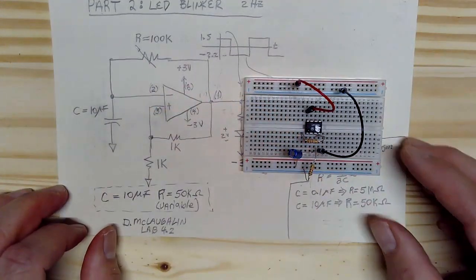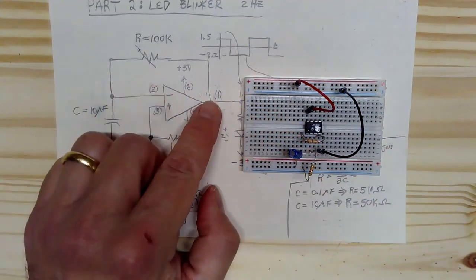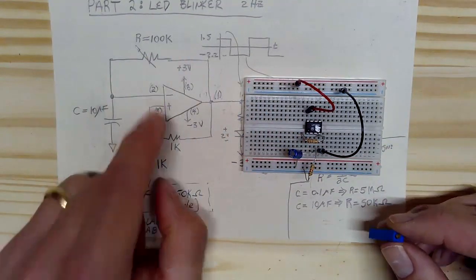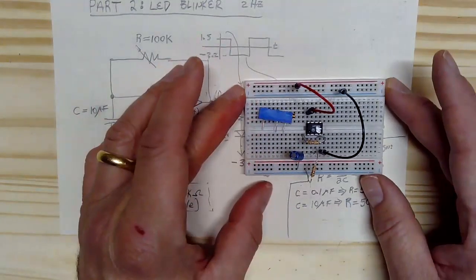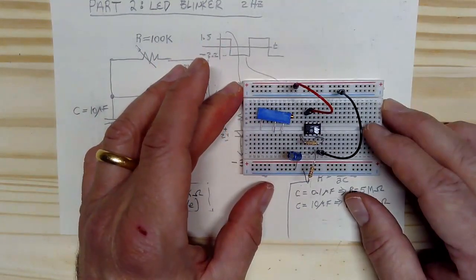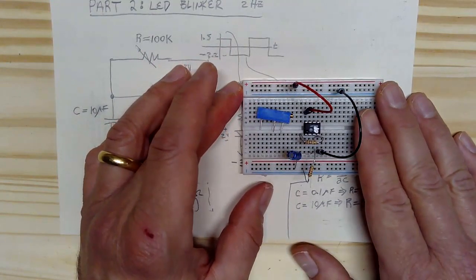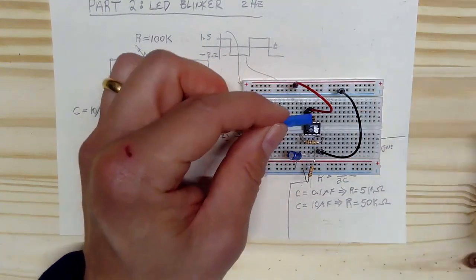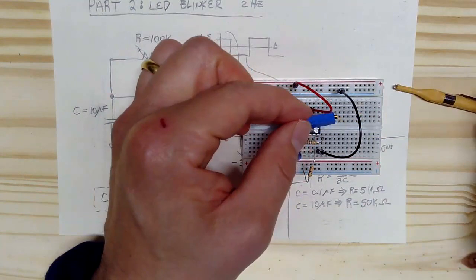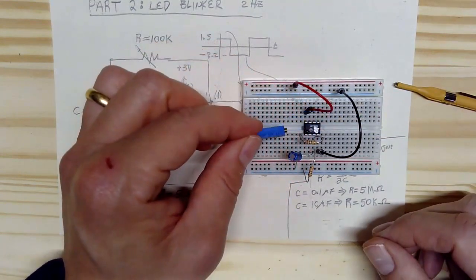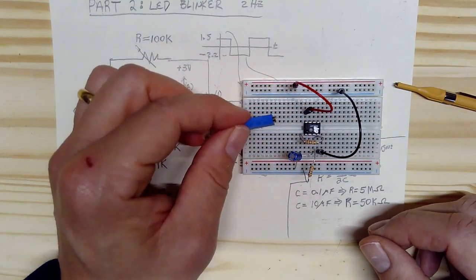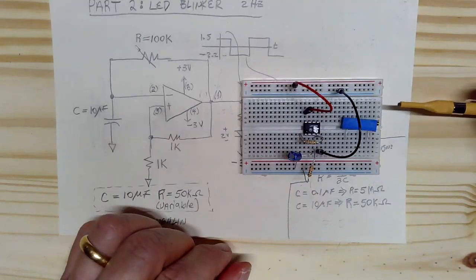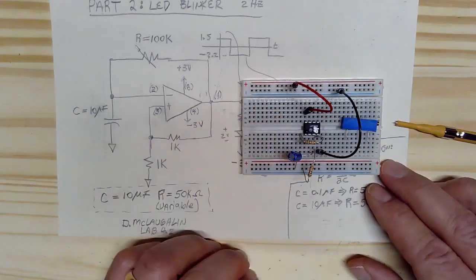Okay, now we also have to put in our variable resistor, and that's going to go between pin 1 and pin 2. And so now we have to decide where we want to put this. This is a question where we have to do a little bit of planning. We know we have to have a couple of LEDs. That's the output side of this board. And we also know that we have to put this variable resistor somewhere in such a way that we can get our pot trimmer in there to adjust the blink frequency. So we have to think a little bit about where we want to put it. I'm going to put the variable resistor on this side so I can adjust it as I need to, and then I'll put the LEDs over on this side.